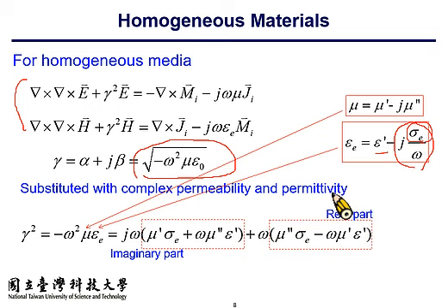So they do not provide signal attenuation. By comparing the representation of permittivity and permeability, you can have a general idea that the second part stands for attenuation in magnetic material, while the first part stands for phase variation, the magnetic dipole moment rotation within the magnetic material. In most of the materials that you will encounter, mu is simply a real number, mu prime.